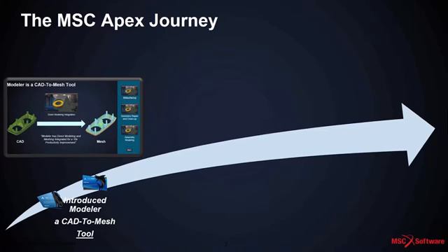As you all know, we introduced in the early releases of Apex the modeling, which was predominantly targeted for CAD to mesh, and you all have seen how powerful it was and it is in creating the mid-surface modeling of most complex geometries, and also it is powered with what is called direct modeling with push-pull technology and edge and vertex track. And more importantly, it was always how easy it is to use and easy to learn.